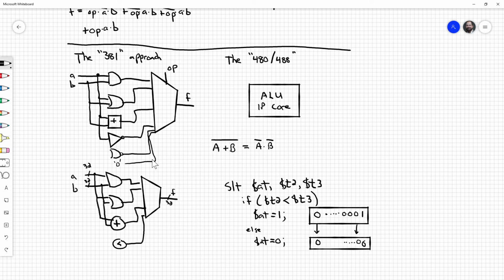So far so good, right? So for 31 of my 32 bits of my bit sliced ALU, the value is 0. And so we still have to have some way to specify that, but we do have that nice optimization available to us there, that it's always 0. It's only the least significant bit. So this would be a design for kind of bit n. If it were to be bit 0, then we do need to have some input to the circuit that specifies that this is less than, that the result of a comparison was less than.